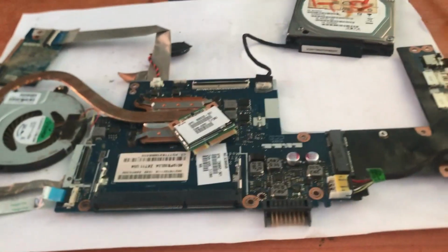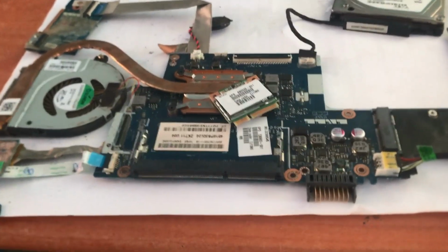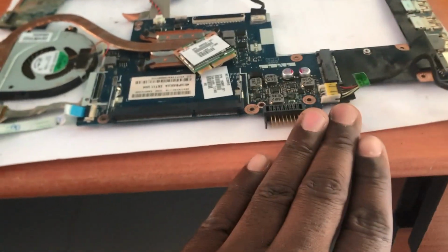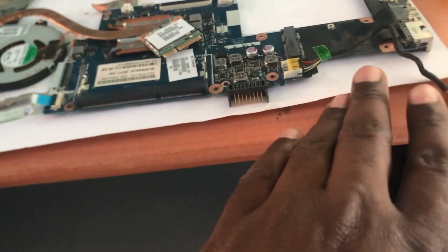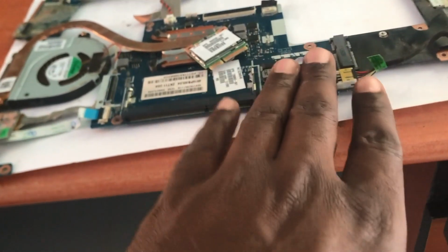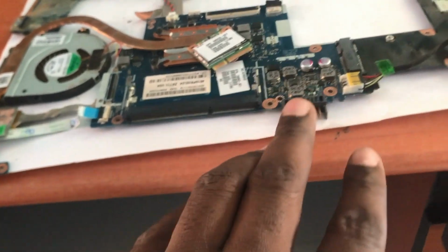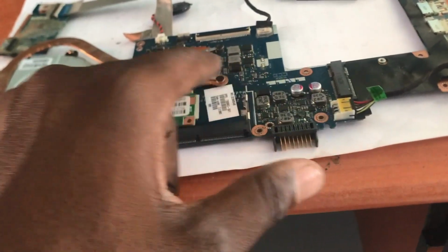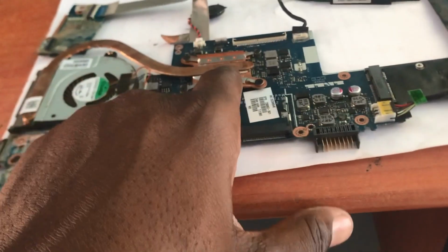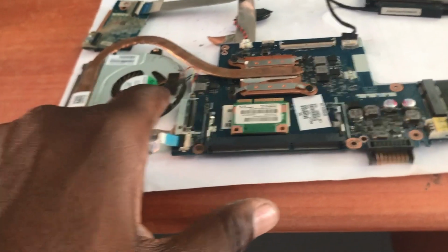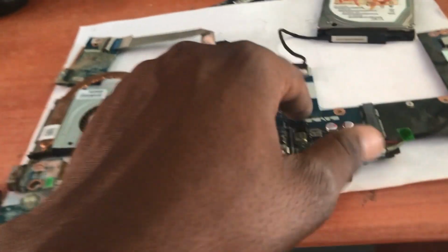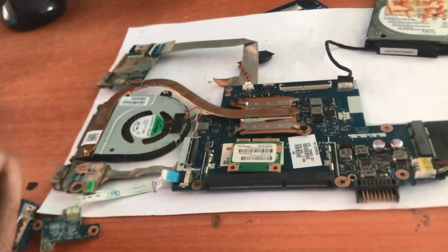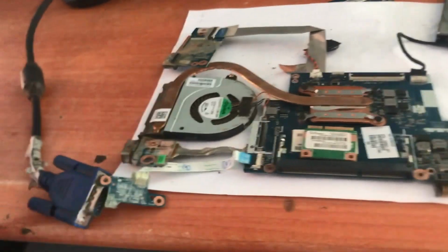Now, being a laptop, all those things are put as one. What you can get to notice is the power flow. Power comes here. When the power comes, probably 19 or 20 volts will enter your computer and be dropped down by the capacitors that you're seeing here, demarcated. Part of it goes to charge the battery, part of it comes to the processor here. Your processor will start distributing. From here you see power for the fan, power for charging the USB ports, power to go to the hard drive, power to other extended USB ports, and external connectors are also powered on.